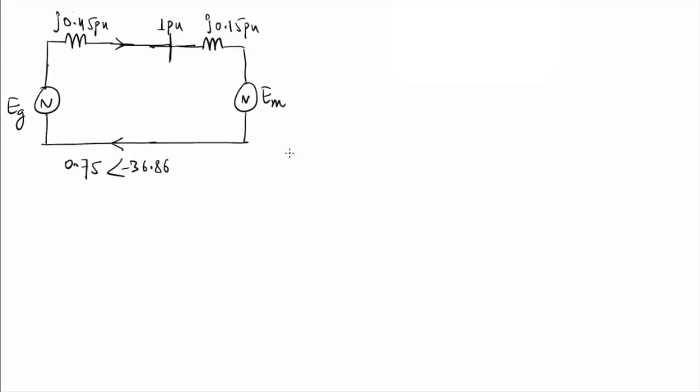What does Thevenin equivalent say? See, this is the diagram that I drew, that is during pre-fault. Pre-fault means before the fault; the reactance diagram was something like this. During pre-fault the voltage across bus 4 was 1 per unit. By using the substitution theorem, I can say that this is at 1 per unit, with polarity something like this. I can replace it like this, or I can attach one voltage source whose value will be 1 per unit at this bus 4.